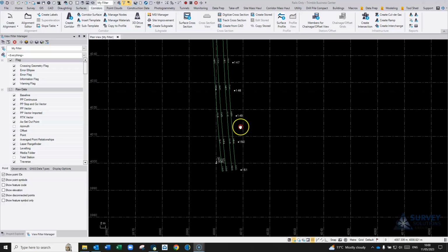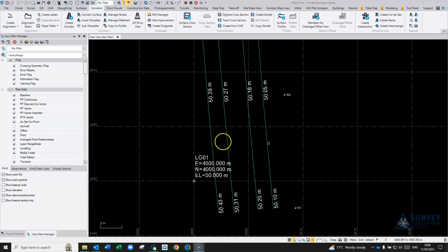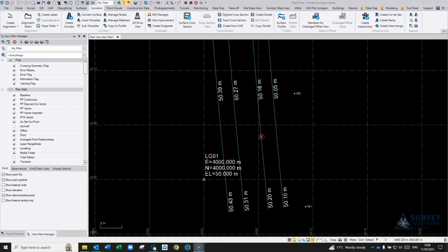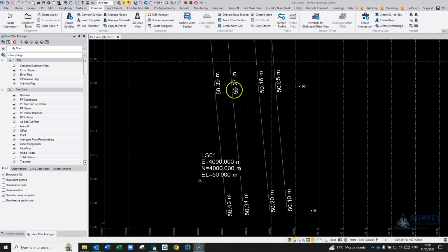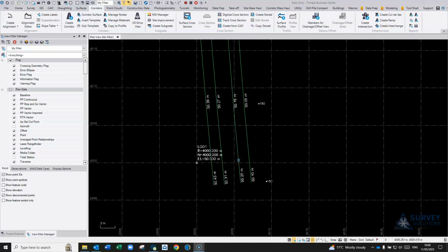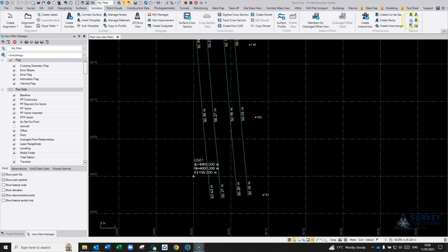So in TPC, I have a project here. We've processed 2 tracks, so we've got 4 rails. So if we're looking to do some basic checks here, just on the gauge and the cant, one of the functions we can use is the chainage offset elevation report.